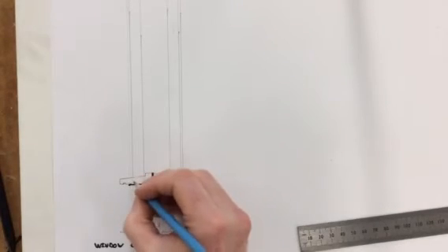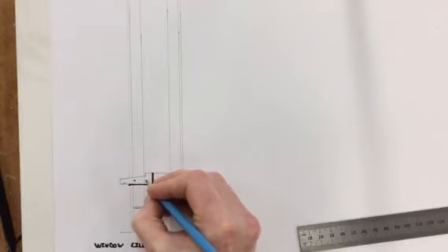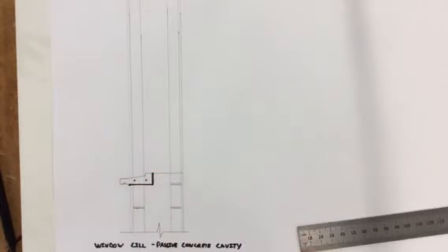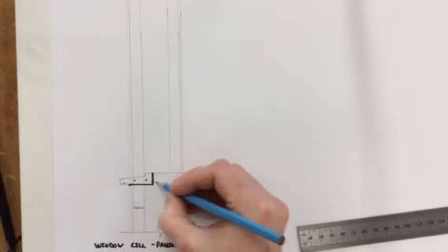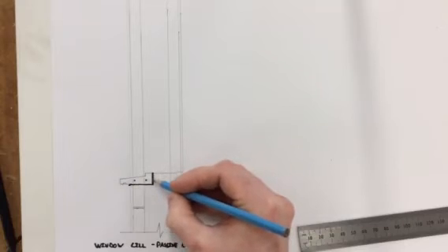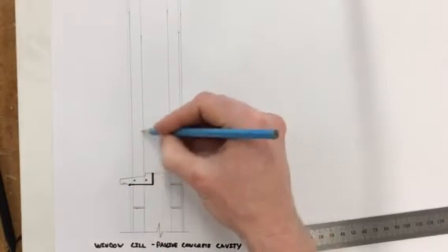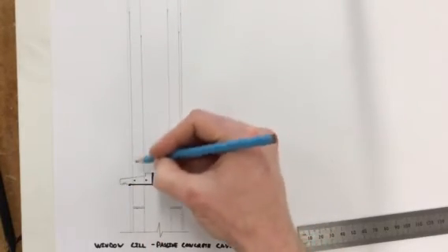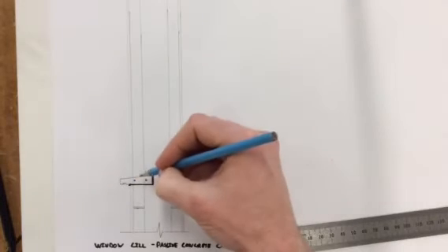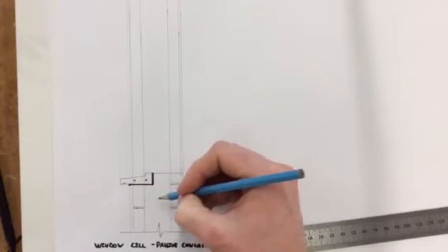You could also have, for example, a couple of reinforcement bars going through that windowsill as well. That's one thing that's very important there. So you have your DPC wrapped around the windowsill because the window frame is going to be here when we get onto that part, and then the rain comes down. You don't want it coming through that and into the insulation.